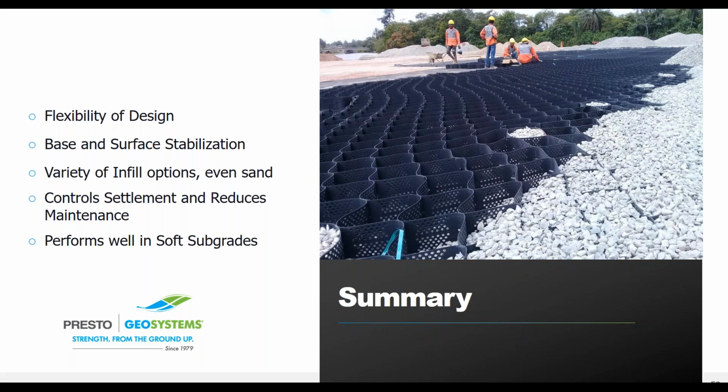Okay. So in summary, the GeoWeb load support system can be added to projects to provide a more stable and durable surface for unpaved areas, reducing maintenance and lifetime repairs. And then for paved surfaces, including asphalt, reinforced concrete and roller compacted concrete, the GeoWeb system reduces the pressure on the subgrade to reduce differential and long-term settlement, which is going to extend the lifetime of your pavement.